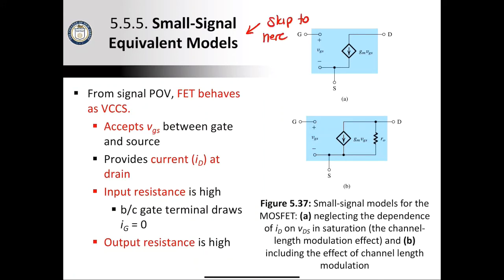The leg room is going to be the component of the input that mostly determines the swing and what the gain was, right? We'd already defined all of these. The output is going to be shifted from the input by 180 degrees. We already said that the gain was negative. There's not much new in there. We defined the gain as negative gm RD. That's the same as negative Kn VOV RD. We've already said all that.